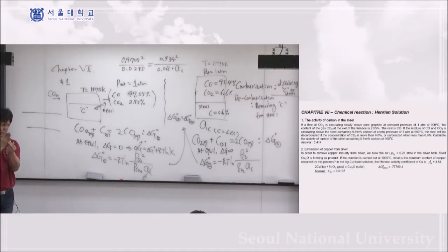So one side, where you are cutting, is very, very hard. And typically, when you add more carbon, it becomes harder, but it becomes brittle. And the other side is ductile, so you have less carbon. Okay? So how are we making it? We make the entire thing, and then we put a cover here on one side. Initially, the carbon content is, for example, 0.1% for all the steel.